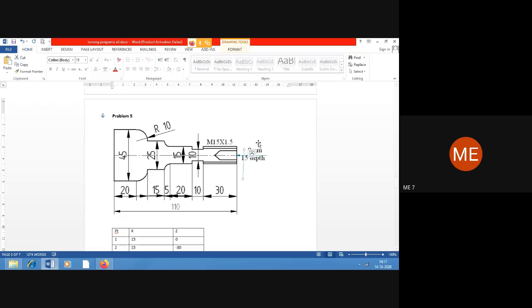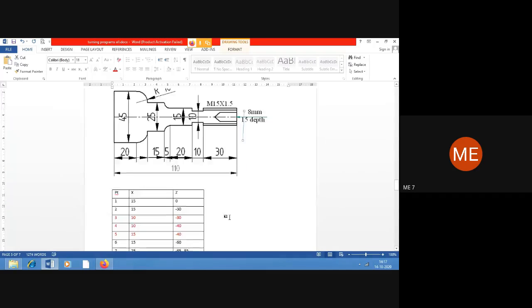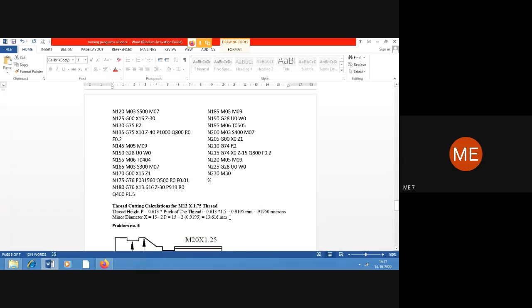Okay, we need it, that is X is going to be 0 and Z is going to be 1 or 2 mm. That means on the right side, there will be a gap between the right hand side end of the workpiece and the drilling tool tip. So thereby, to get the tool horizontally exactly at the center, X is 0, Z 1 or 2 we can give. So next, the new portion is drilling cycle syntax.